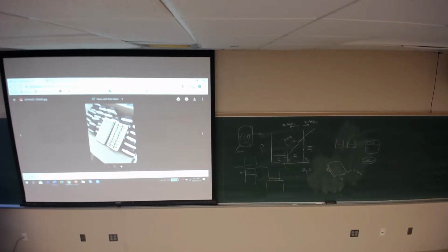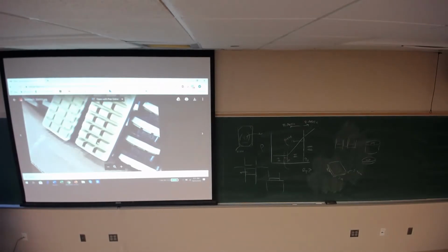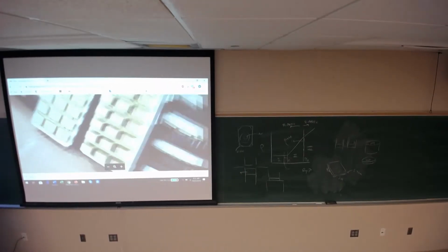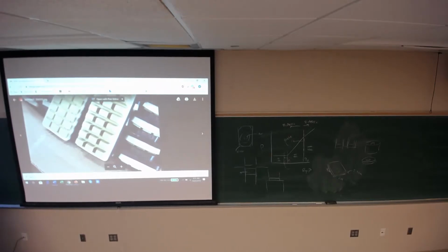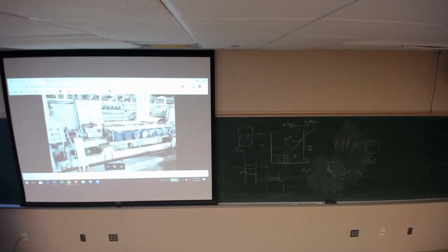And then this is how they polish. So these are abrasive packets, and they're set up, and they're spinning, right? They spin, and the tile comes in, and they polish the tile flat. When they're all done, this is where it starts, that's where it ends, and they take them off. And the 800 here indicates a grit size, and they polish all this tile. This is a polishing line.